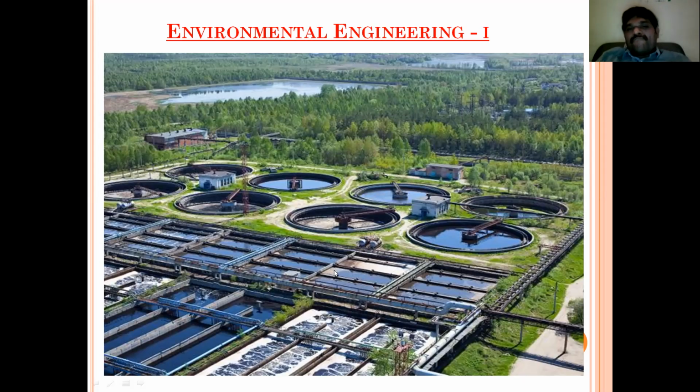In the step by the name of sedimentation, we are not doing anything. We are allowing water to stand without disturbing it for a period of time. By doing so, the particles whose specific gravity is more than the liquid will settle at the bottom. After a period of time, the settled particles will be taken off and the water will be sent to the next unit.